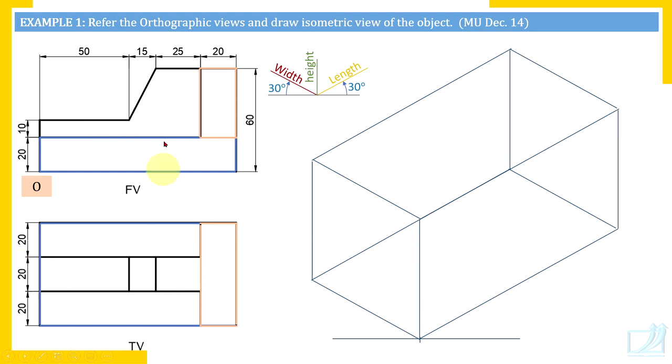The reason is, these two dark lines are for these two corners. You know that a corner is formed by three edges. So these two edges are meeting at this point. So where is that third edge that you get in the top view? That means this plate is here at the center, placed symmetrically between the blue plate and the pink plate. Okay. So there are clearly three plates. This is that plate.